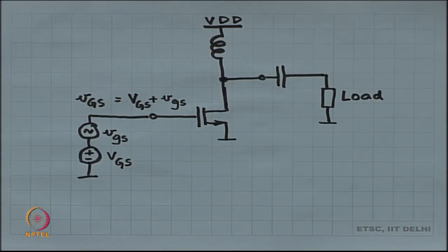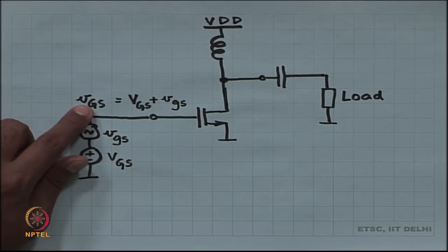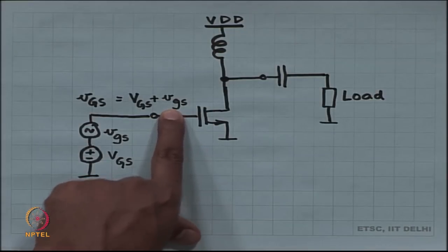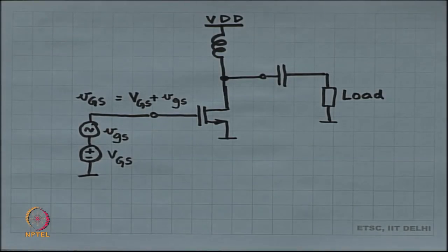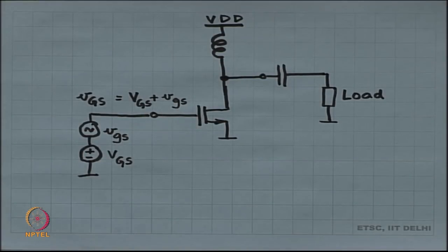So, if you remember our convention, small letters subscript capital letters is something which is the combination of both the small incremental signal plus the DC operating point. Small subscript small was just the incremental signal, capital subscript capital was the DC operating point. Okay. So, this was our convention. The only one that is not over here is capital subscript small, and capital subscript small is nothing but the Laplace transform of small subscript small. Okay. Just reminding you, refresher.